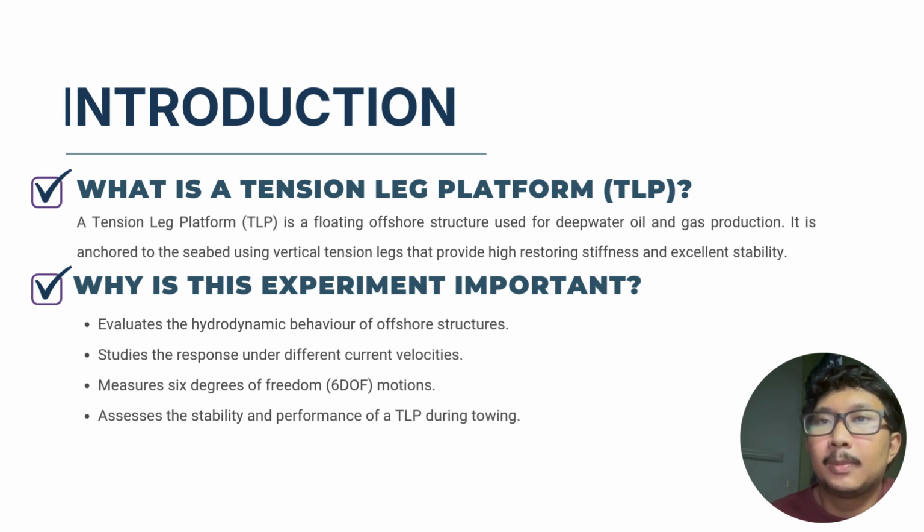So, why is this experiment important? It evaluates the hydrodynamic behavior of the offshore structure. It also studies the response under different current velocities. It measures 6 degrees of freedom motion. It also assesses the stability performance of the TLP during towing.